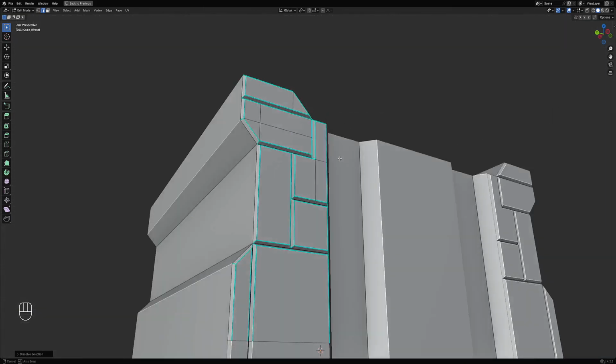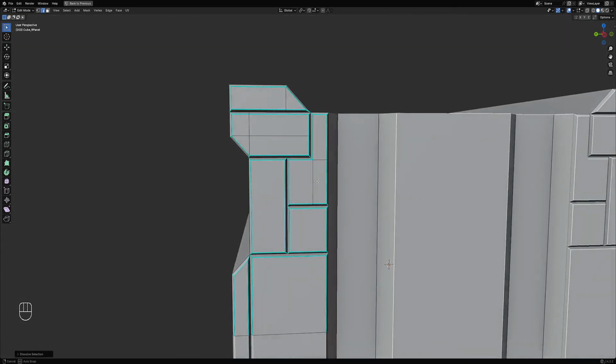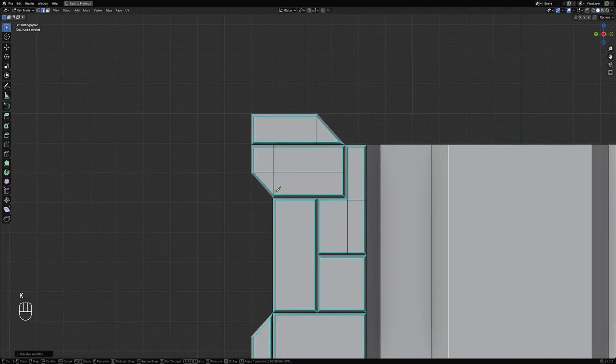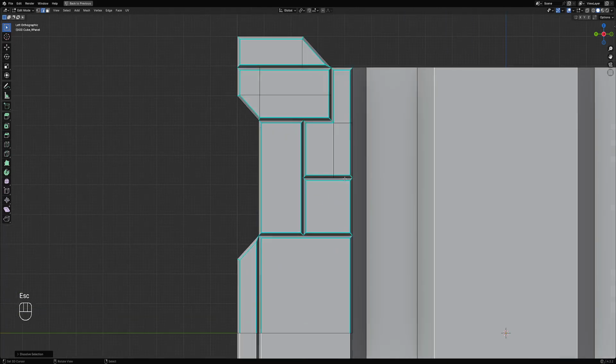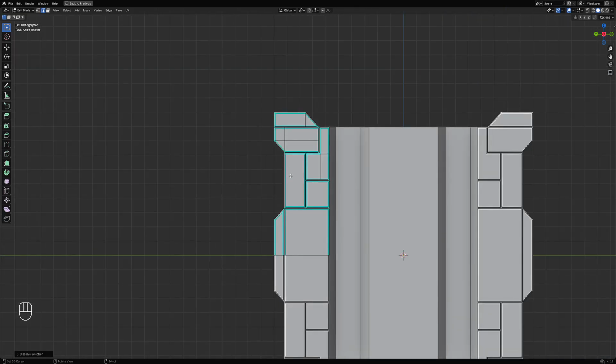So it's faster this way, because you don't have to use the knife every time. And the knife is good. The knife in Blender is actually very functional and very good, especially now in 4.0 plus. But for some complicated setups or topology, the quad slice can work better.